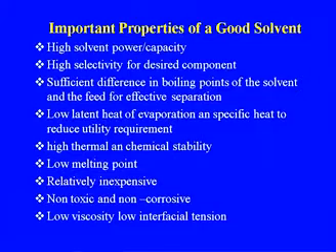High solvent power capacity, high selectivity for the desired component, because that is the component which has to be removed, sufficient difference in the boiling points of the solvent and the feed for effective separation, low latent heat of evaporation, high thermal and chemical stability, because stability is also very important as in some cases we are using high temperature, low melting point, relatively inexpensive, non-toxic, non-corrosive, low viscosity, and low interfacial tension.